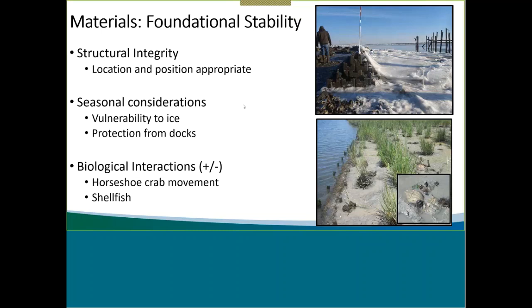We want to use sacrificial materials that are less costly, that may be destroyed, to protect the materials that we really need to keep in place. But are you in a site that has seasonal docks? You may feel protected in the summers, but in the winter when they take them out, you're going to get the increase in energy, and you're going to get ice coming in. So when you think about that protection when you're doing your site evaluation, as Jesse was talking about earlier, think about seasonality too, where there's things that are in place in one season that may not be in place in the other. It'd be great if someone put docks in the water in winter to protect it from ice and took them out in the summer, but they don't do that.